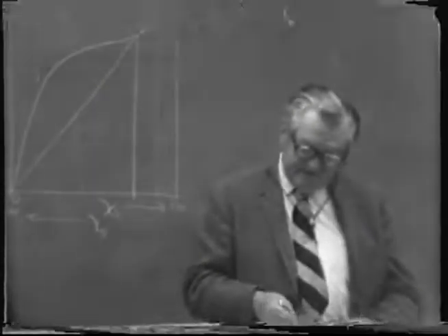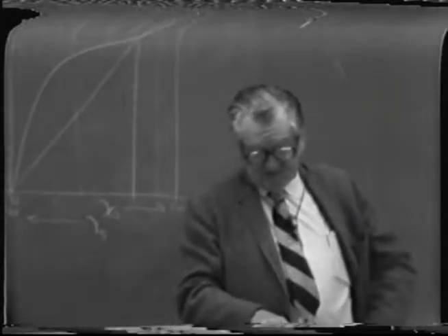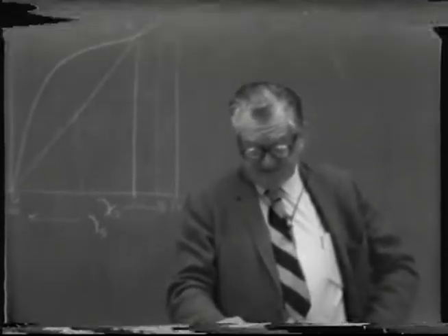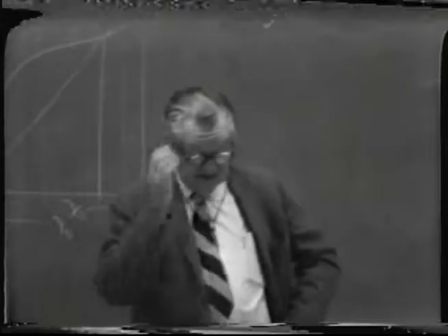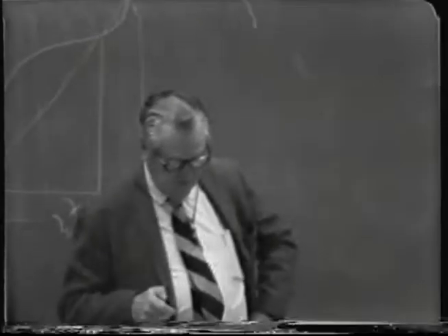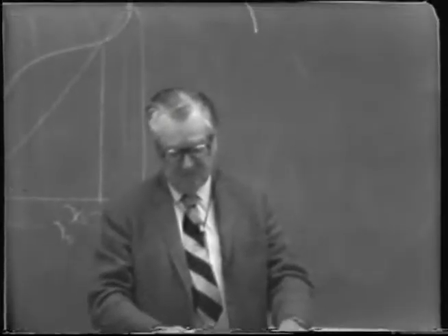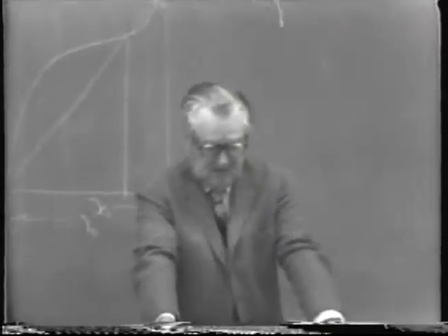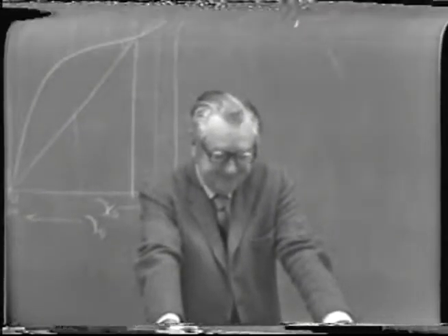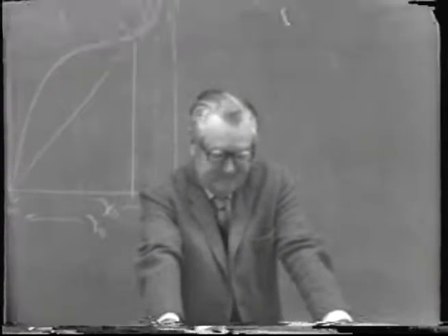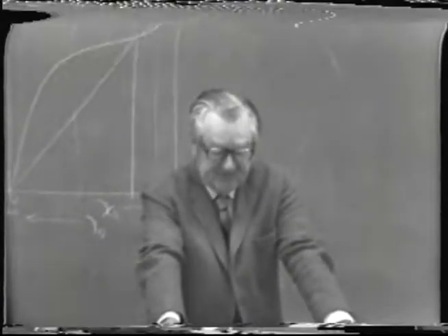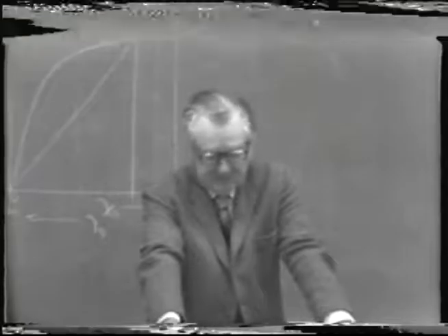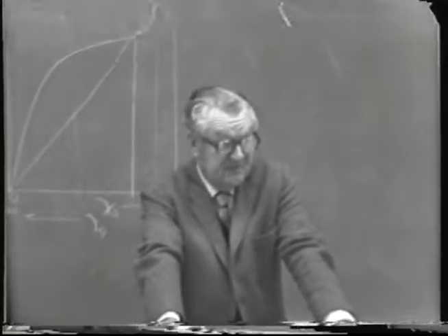Anyway, I've calculated there for both 10% ethyl alcohol and 95% ethyl alcohol, and by the 2 methods, A and B. You see that although they don't agree perfectly, they're the same order of magnitude. So one could say that the appropriate vapor velocity, if you only had 10-inch plate spacing according to this method, is only about 1 to 1.5 linear feet per second.